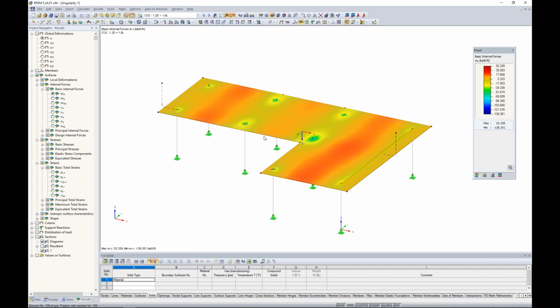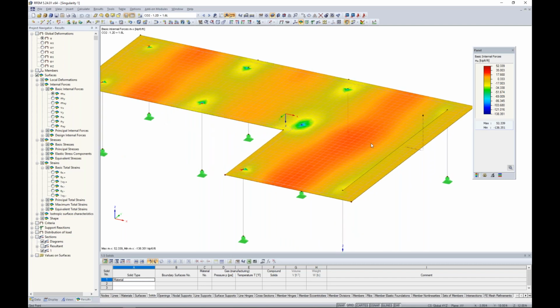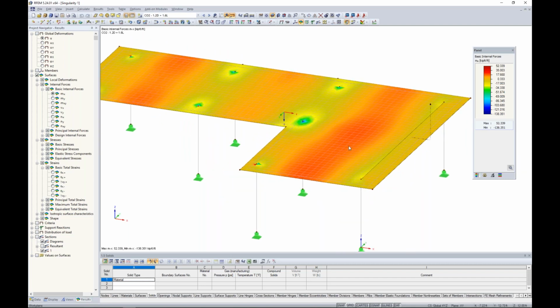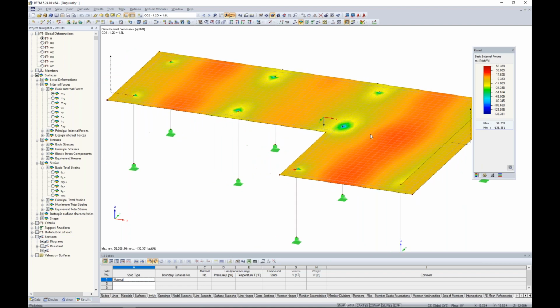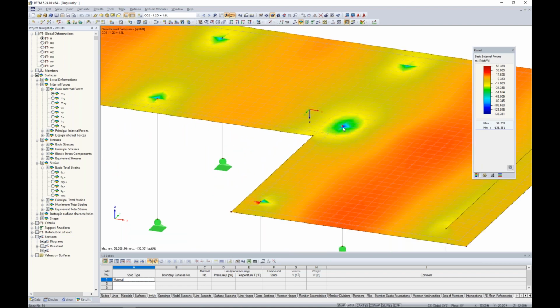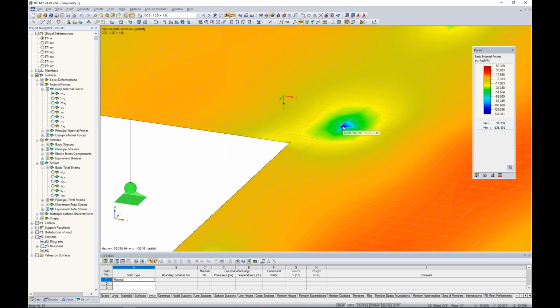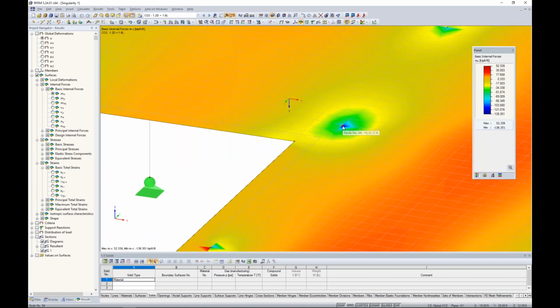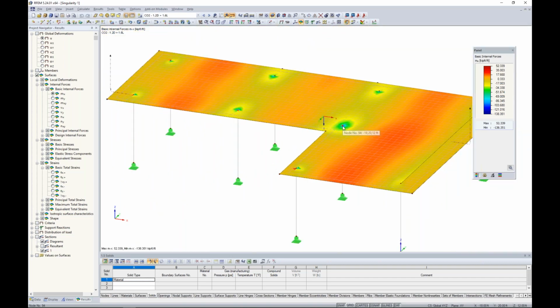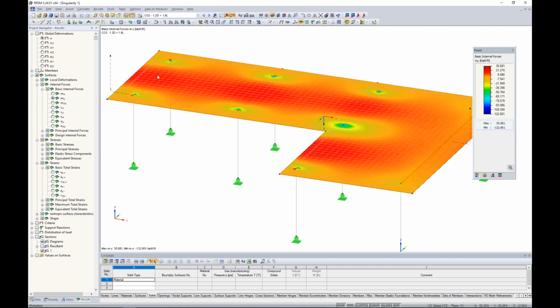Initially, MX looks okay. Obviously we're seeing some positive bending moment in between these column supports. But then there's the case here over the columns where we're seeing extremely high negative bending moments. And of course, there will still be some negative bending, but these look to be pretty high at these locations. MY, same concept: positive bending in between where these columns are spanning, but then very high negative bending moments where it frames into these single 1D member elements.